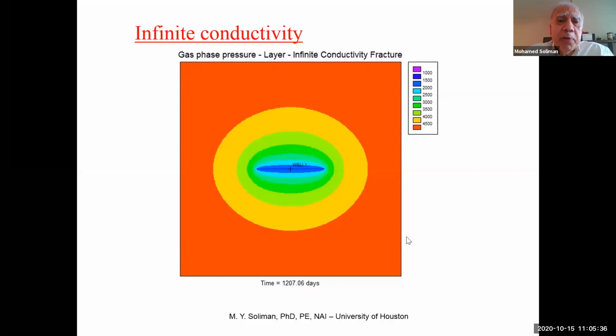you can see the pressure drop around the formation is demonstrated here. If I look at the outer boundary where the pressure has been significantly affected, the rest, the red area, basically says we have not affected this area at all. So nothing, or very, very little, is coming out of this red area. Most of the fluid is coming out from this affected area. And if you look at the affected area, it's elliptical in shape, but it looks almost like a circle. So it is almost radial flow, and this is the reason you call it pseudo-radial flow.